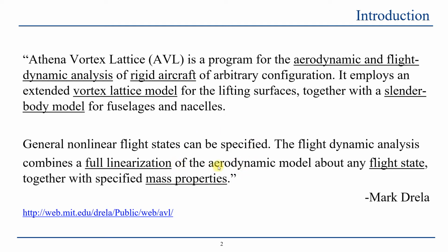We will get to what are the files required for any of your simulations, depending on how in depth you want to be, but usually you need three types of files. One is the geometry of your aircraft, one is the run case for your aircraft, which basically simulates a scenario in which you want to simulate your aircraft or flying object, and another one is a mass file, which includes the mass properties of your object or design, which basically helps with all the inertia and other parameters that relate to the mass of your object.